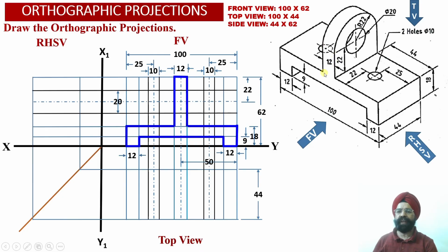So the observer will be able to view the true shape of this vertical web up to the center point over here. So this surface is also true shape, but the surface which is lying above the center line over here, because this is corresponding to a semicircular arc which is available with us at the top portion of this vertical web.